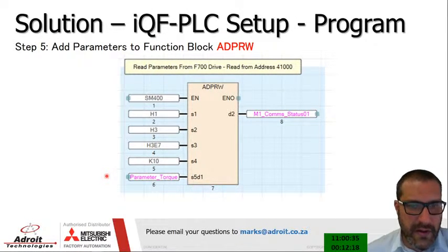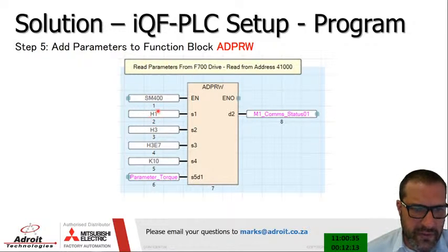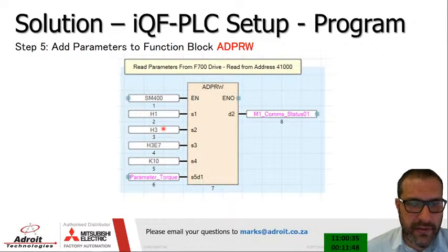Okay, so remember I said earlier H1, that it's always in hex, by the way. Well, not always. PLC likes it to be in hex. So hex 1, that is the address that you're talking to, the PLC address. So you want to talk to H1, which is VSD address number 1, Modbus VSD address number 1. H3, that's the parameter that we want to use, that we spoke about, the function code. It's going to be H3. In other words, we want to read from this device.